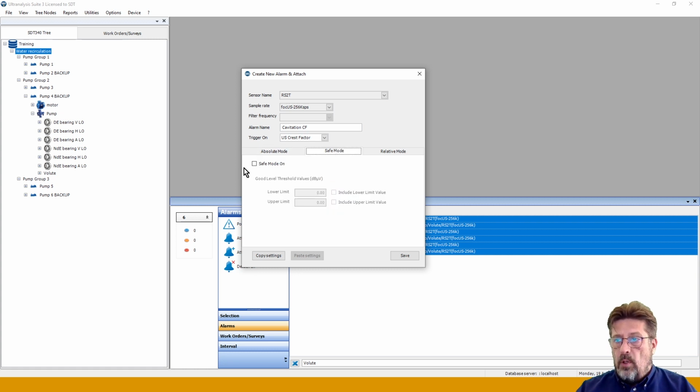Now, of course, the safe mode, I can also say, if crest factor is less than 3, that's not going to be realistic, honestly, because if crest factor is less than 3, I have a reason to suspect that the signal is clipped. So it's a good idea to have this alarm on crest factor, because if you have crest factor 2, there is a high probability that the signal is clipped. And the upper limit, I can just invent it now and say 60. Everything in between is, let's say, okay measurement.